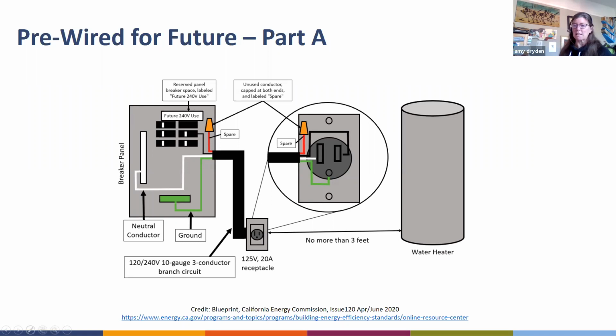So anytime you see a gas or propane water heater, you're going to be looking for capacity at the panel. You can be looking at the electrical schedule if you're doing plan review, and field inspection to actually see it installed.